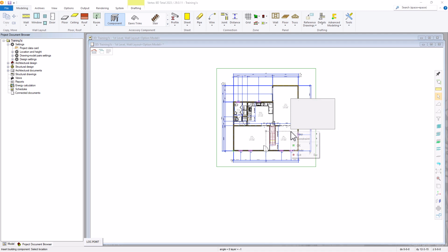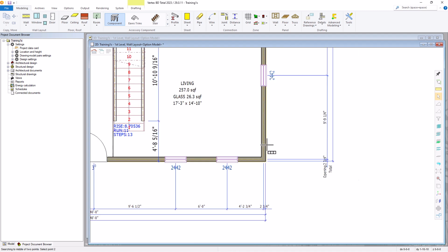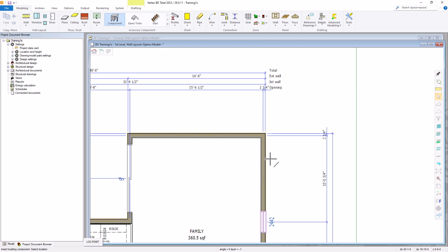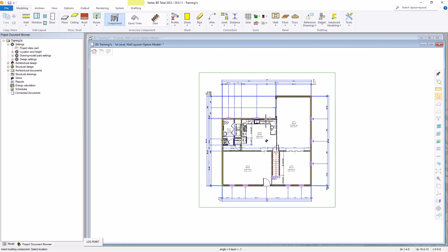So we'll right click and go to Snap and select Middle, or you could select the D key. So I'll select Middle. And now we'll select 2 points and we'll select the framing point of this exterior corner and the framing corner. And now we should see an alignment marker centered in this drawing.